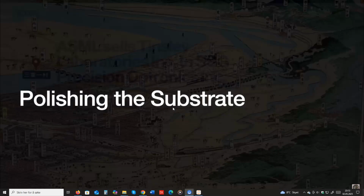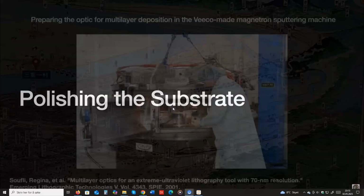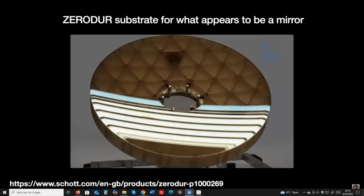Recall from the start of this video that the mirror has to be polished down to 50 picometers RMS. To be honest with you guys, the major obstacle to the mirrors had less to do with the molybdenum and silicon layers, though still tricky. The pioneering deposition work was already getting close to the maximum theoretical limit by the early 1990s, and various X-ray telescopes are already using it with acceptable parameters. What was harder was polishing the substrate to the proper flatness, a challenge enhanced by the fact that Zerodur glass ceramics are not suitable for polishing and that the mirrors are not simple spheres. They exhibit many different surfaces to achieve their optical purposes.